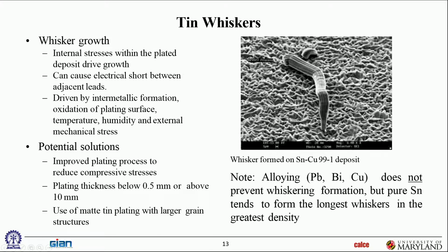You try to reduce the amount of compressive stress, because remember I drew a sketch of the steps that we hypothesize are what's causing tin whiskers. We believe there are pores in the oxide layer. We believe there's compressive stress in the tin underneath, and it's that compressive stress that's extruding out these single crystal whiskers through grains that are correctly oriented. There are some grain orientations where you cannot grow whiskers very easily because that's plastic flow. Plastic flow only happens in certain crystal directions. So if the crystal underneath that pore happens to be oriented in the right direction and has the right amount of stress, it'll shoot out these single crystal whiskers.